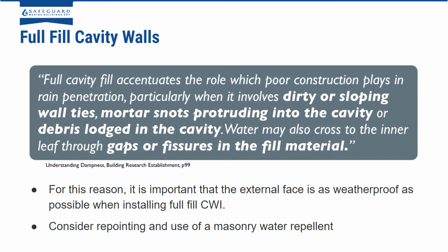So this statement by the BRE makes that point. If I read it now: full cavity fill accentuates the role which poor construction plays in rain penetration, particularly when it involves dirty or sloping wall ties, mortar snots protruding into the cavity, or debris lodged in the cavity. Water may also cross to the inner leaf through gaps or fissures in the fill material. Because of this, it's important that the external face is as weatherproof as possible when installing any sort of CWI.